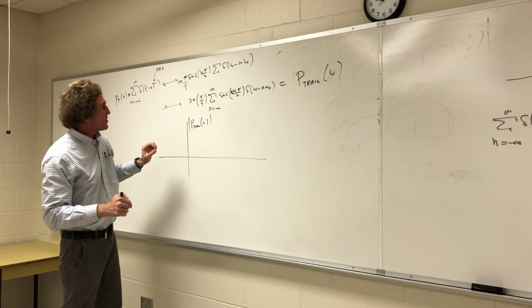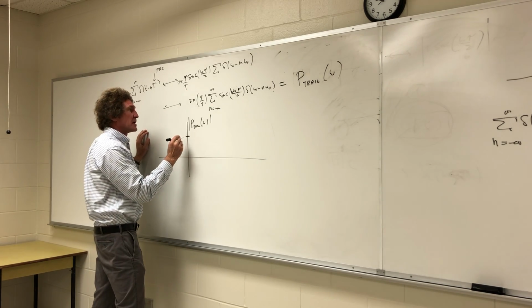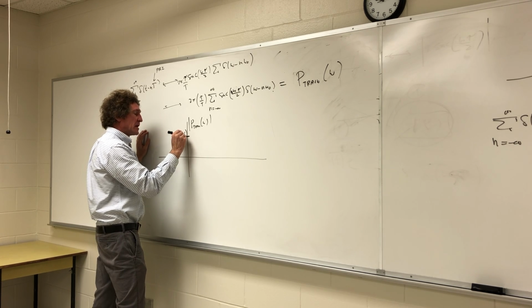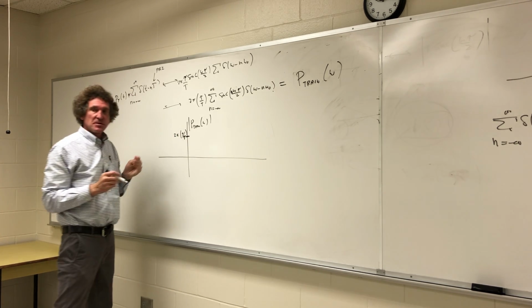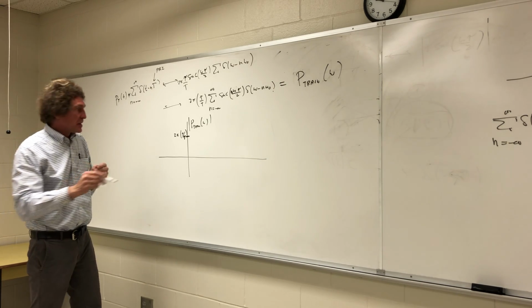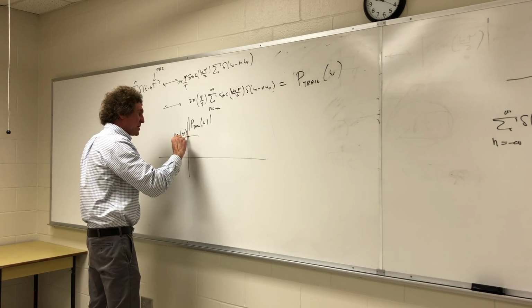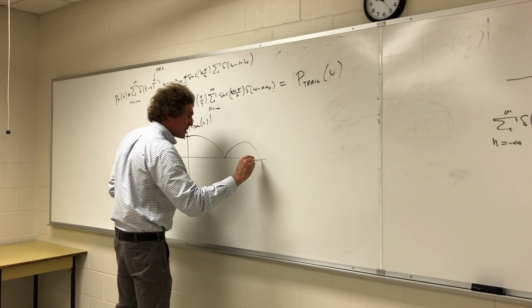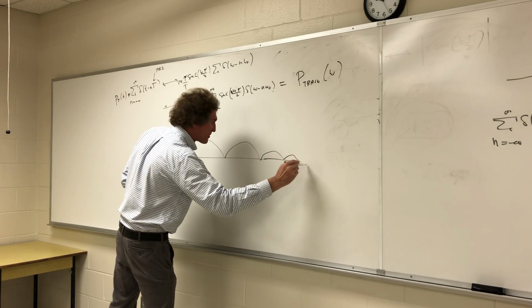Now, that means it starts with this amplitude right here. It's 2 pi times tau over T. And that's really just the duty cycle, correct? Now, what does it do? Think of it as an envelope, right? Let's just take the magnitude of that. And the envelope's dropping down rapidly.